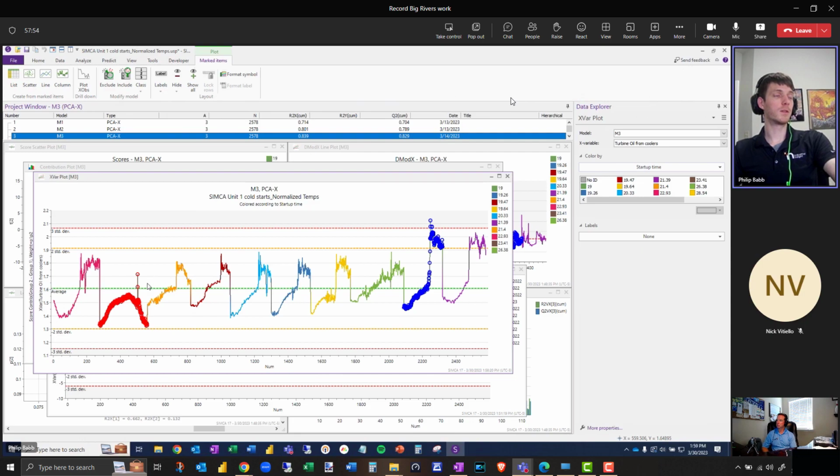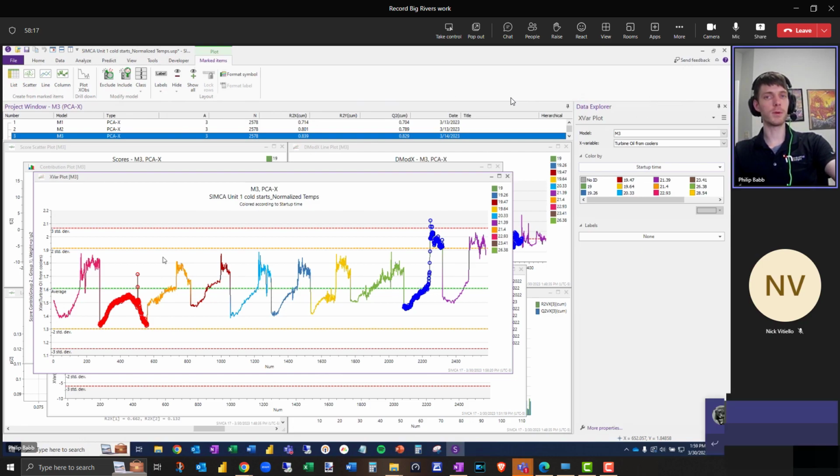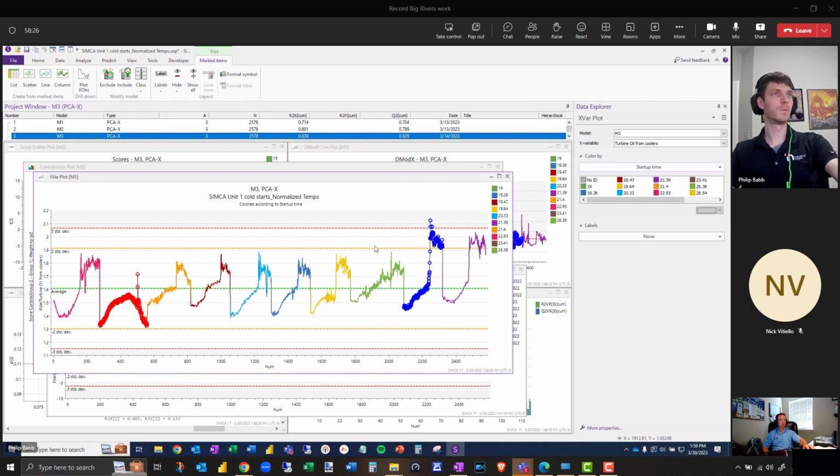But it turns out that this particular measurement, this oil, along with the bearing temperatures, can cause significant delays in the turbine getting up to speed, if I remember correctly. If these temperatures are too high or too low, then they're not able to roll the turbine up. So this variable is a holding point for them, assuming it's out of some range.